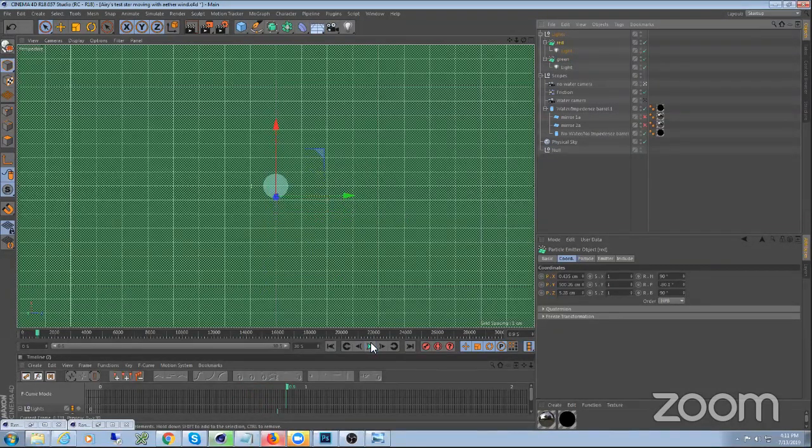And the reason I did that in this way, I typed it in the notes yesterday, is there's two ways of actually getting the same result. To change the vector of the perpendicular light is by creating a wind object, and that will create a diagonal stream of the particles by blowing them to the side. Or the easier way is to just tilt the emitter so it drops it at an angle from the source.